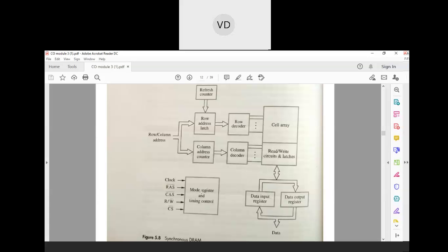When we are doing the complete block of transfer, each block will be having variable length, is it not? So we have to provide the information to the processor or to the memory, what is the length of that burst, or what is the length of that block of data. That information is given in this mode register.